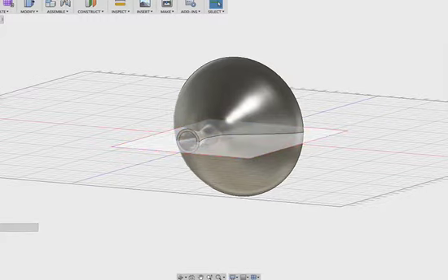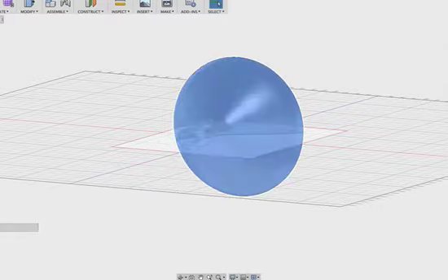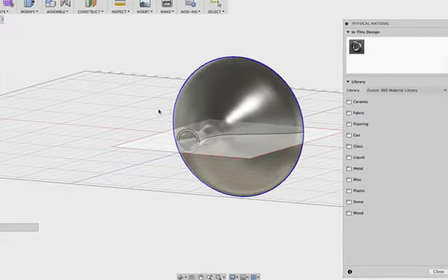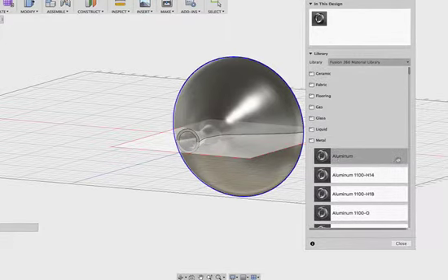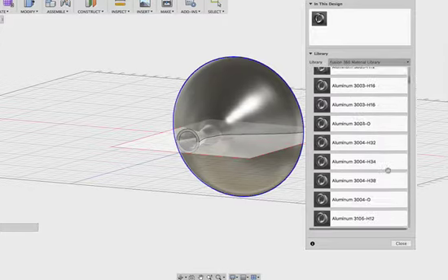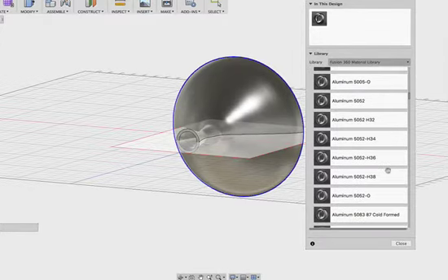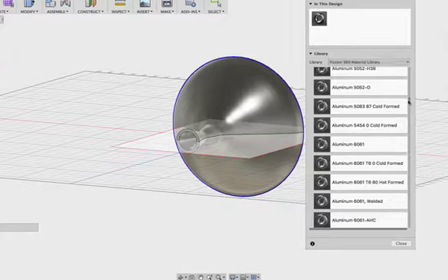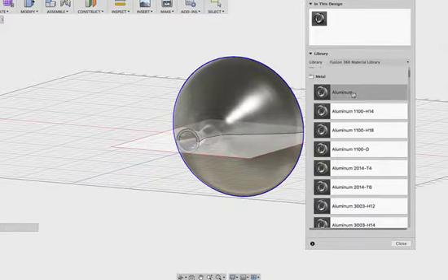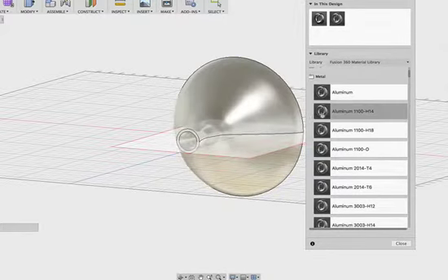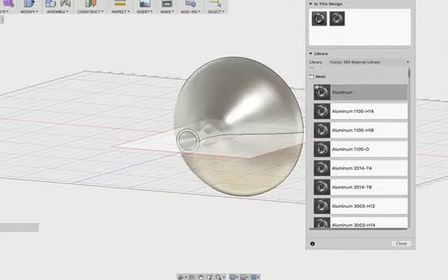And then I'm going to go to bodies. Body 1, there it is. I'm going to select physical material. I was hoping for some aluminum here. Where's this? This is steel. That's fine. Metal, dry aluminum. They have all these different forms of aluminum. So it just shows you can get all kinds. We're just going to go with the standard aluminum. Drag it over that because it was steel. All right, so now this whole thing's aluminum.